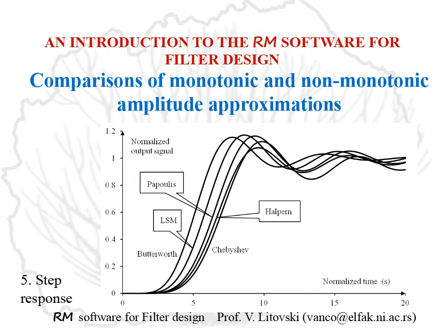Here a comparison is made in the time domain. Here the step response is depicted, and a property which may be extracted here is that the less selective filters have the smallest rise time and the smallest delay time, but they do not have the smallest overshoot and undershoot, while the most selective filters have the largest delay time, the largest rise time, and have the largest undershoot, which is in this case really large.